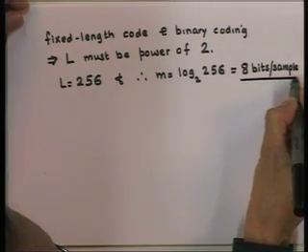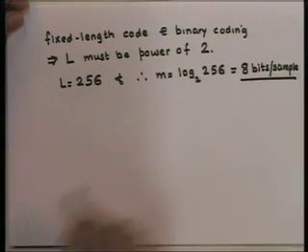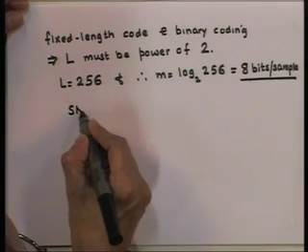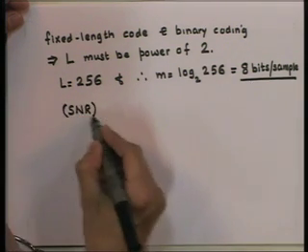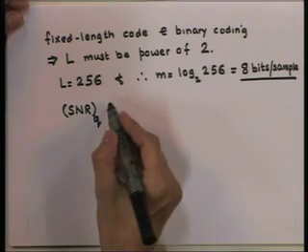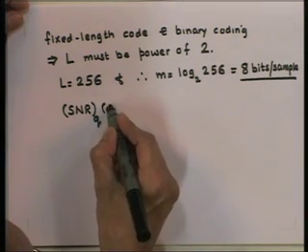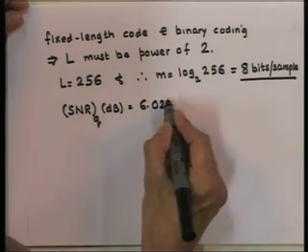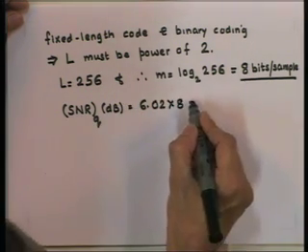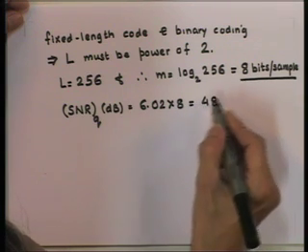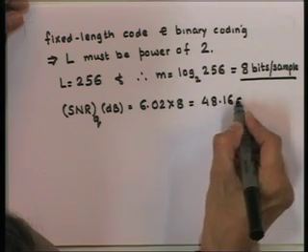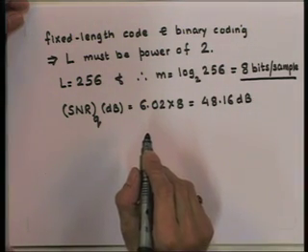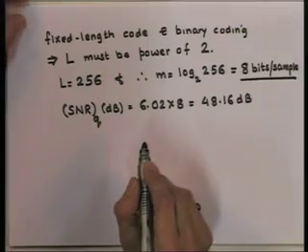So, this is the desired solution, and the signal to noise ratio, that is quantization noise in terms of dB, is equal to 6.02 multiplied by 8 is equal to 48.16 dB, assuming that the input PDF is uniform.